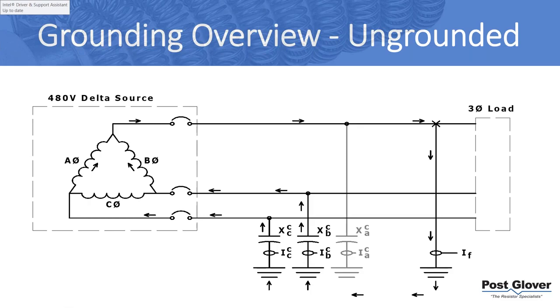At that point, you're severely overvoltage, you're stressing your entire system, and you're probably going to have multiple points of failure at some point, and you're going to go line to ground to line very easily, and you're going to trip with a line-to-line fault, probably some damage, obviously your entire system shut down, etc. Not desirable. One of the main reasons why you don't see ungrounded systems being specified anymore. There's a couple things as well, but that's the main one in my opinion.